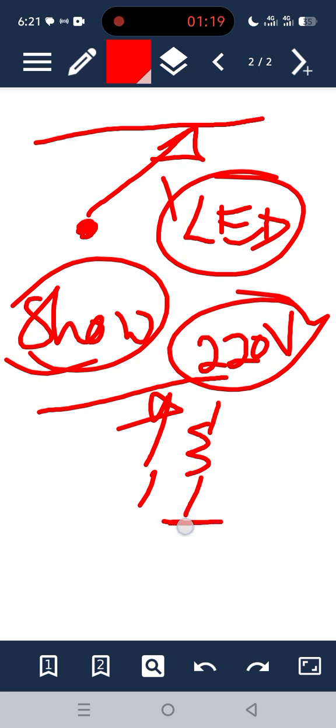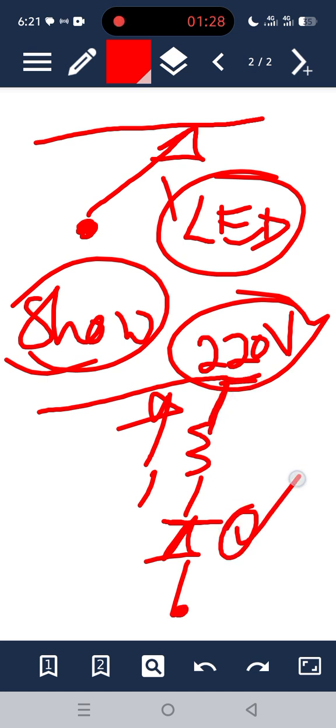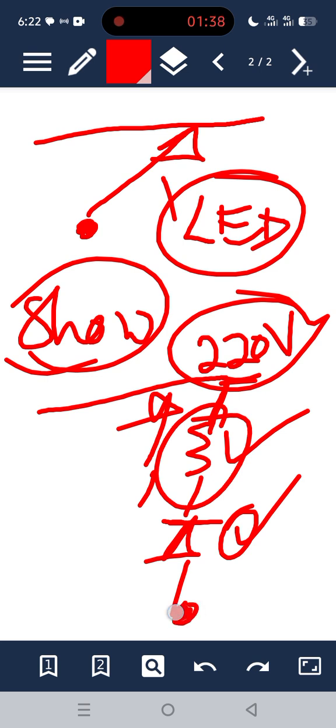So there is an LED over there. Then you touch around this place, the phase tester touches the line, and this LED glows. Basically, the resistor is there to tone down the amount of current, or rather to create a voltage drop, so that the voltage you're touching here is safe for you. So how does it actually work?